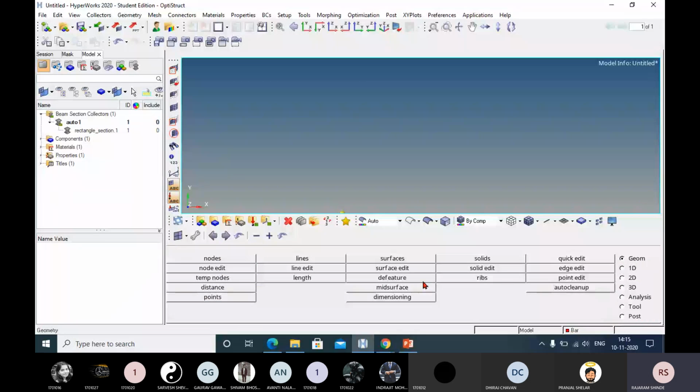Now one thing I want to tell you here, remember, if you make only one element in case of beam applications or bending applications, then you will get constant stress from this node to this node. That means from the fixed support to the free end, you will not get variation in the stress. But in bending applications, your bending moment is varying from point to point. Do you agree with this? So you need to define a larger number of elements.